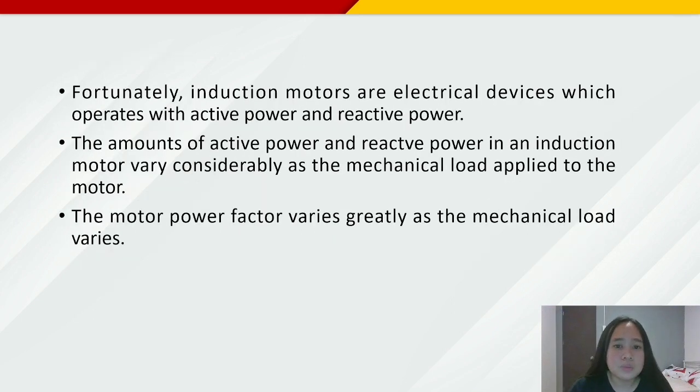Fortunately, induction motors are electrical devices which operate with active power and also reactive power. The amounts of active power and reactive power in an induction motor vary considerably as the mechanical load applied to the motor varies. The motor power factor varies greatly as the mechanical load varies.